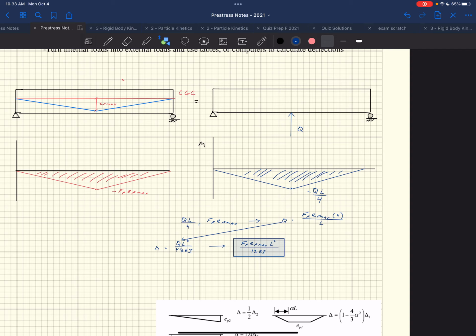And so you'd have to look up, well, what kind of loading condition would give an offset like that. And there'd be a constant moment on either end, which you can look up in a table. That deflection from that one plus this load from the Q. So you do a combo of the stuff. You say, okay, what combos of loads give me those deflections, right? And then it's all in the elastic range. You can do superposition in there.